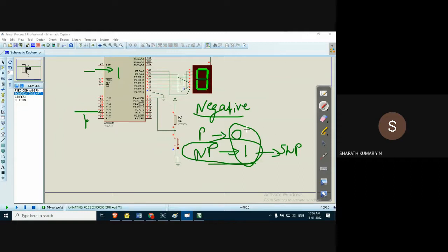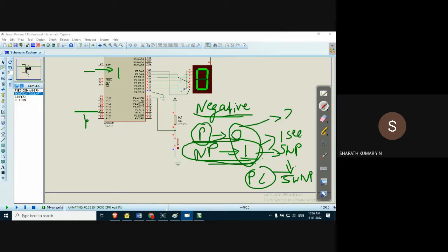In positive logic, this is switch not pressed. This condition is switch not pressed. So when the switch is pressed in the program, which physically means not pressed in negative logic, it equals 1 and will generate a 1 second delay. Not pressed means switch open in negative logic. Sorry, when the switch is physically pressed in negative logic, it sends 0 to the pin, then it will generate a 2 second delay.